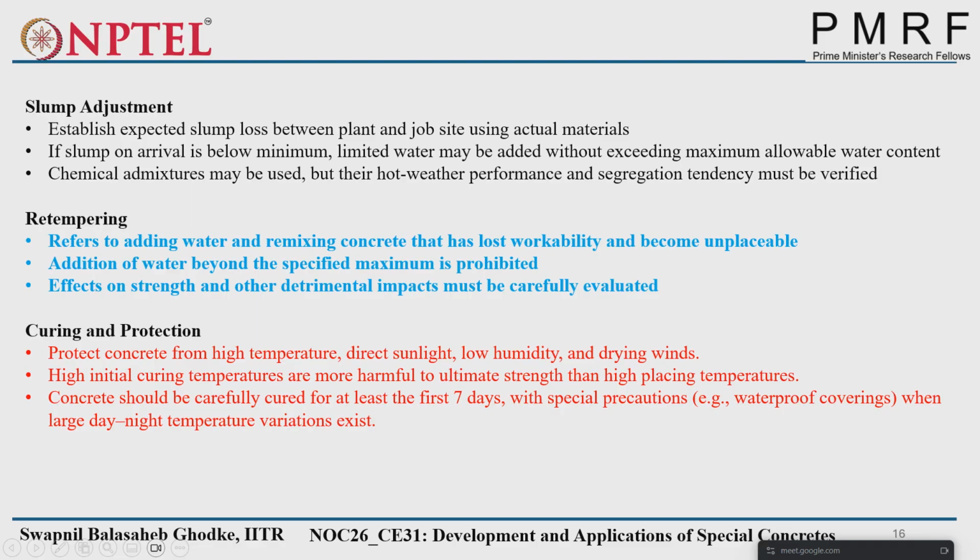High initial curing temperature is more harmful to ultimate strength than high placing temperature. It means that even if we take care of all the hot weather placing conditions, if we are still providing hot conditions during curing, that will have the major impact compared to the concrete temperature itself, because that will again enhance its hydration process.